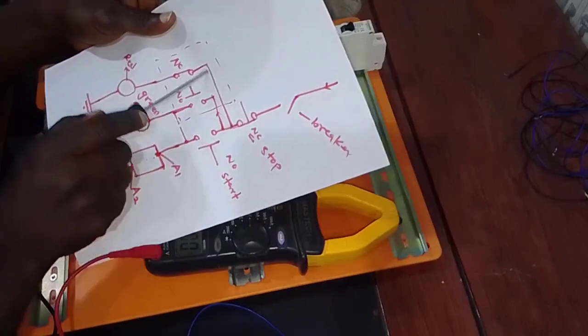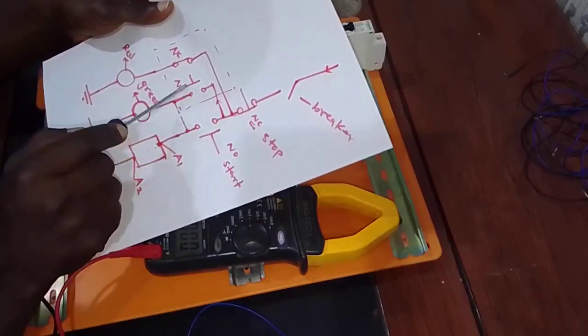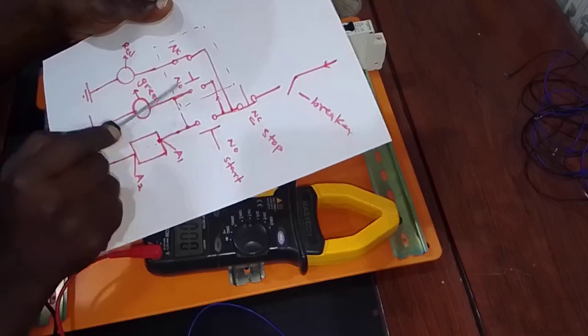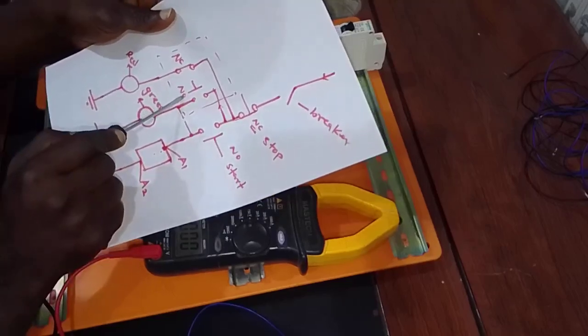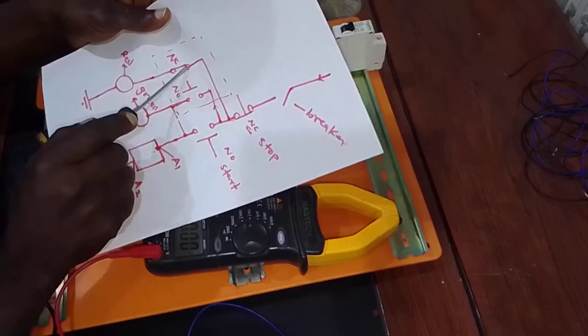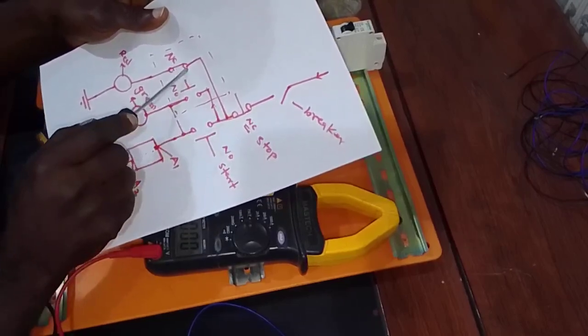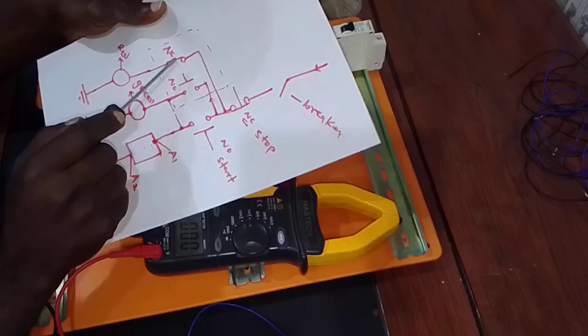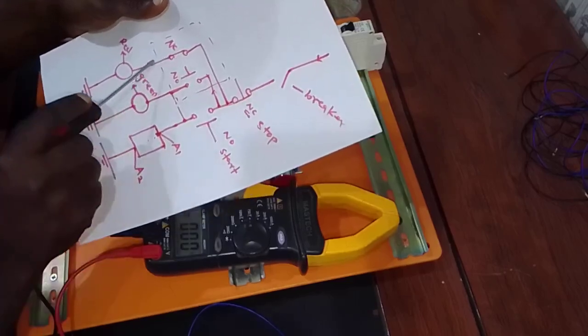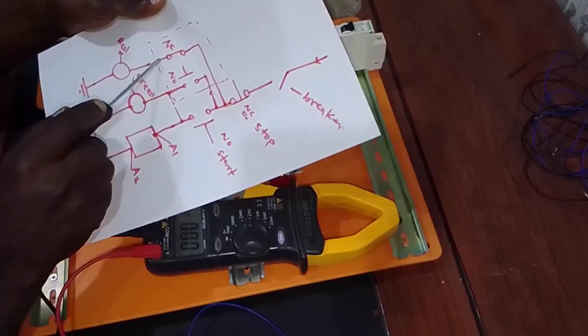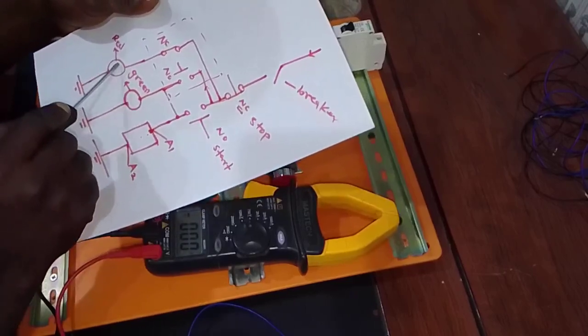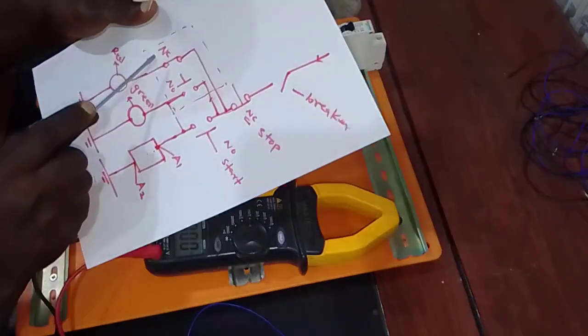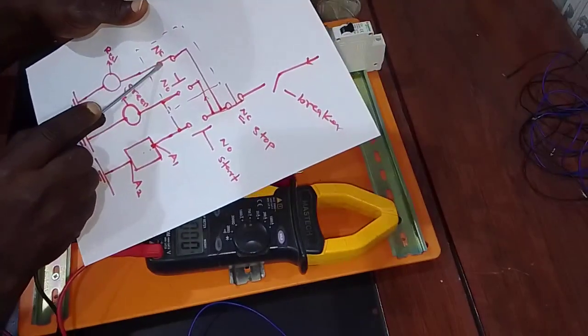We looped from the input of our normally open, we looped the supply there to the input of our normally closed. So now the next thing we're going to do is to connect our red indicator light at the output of the normally closed.